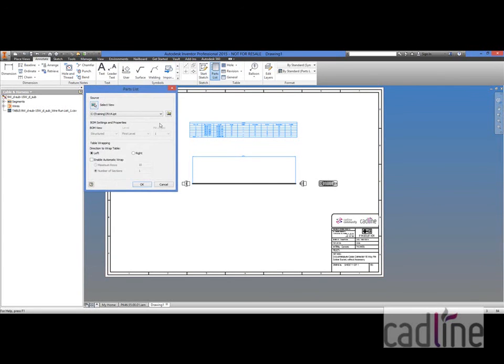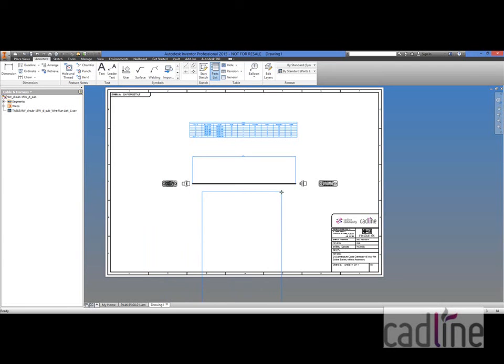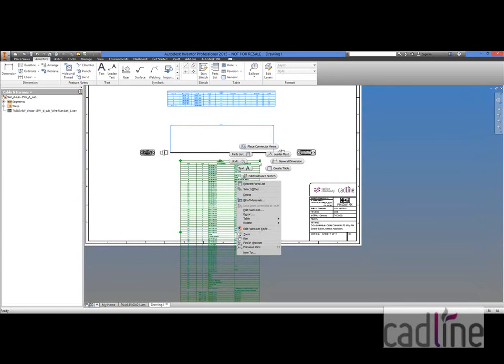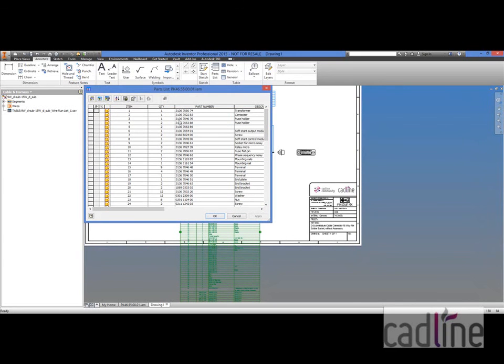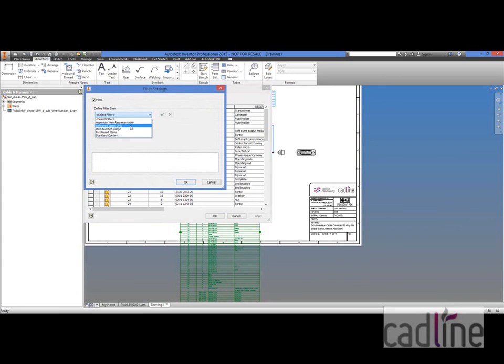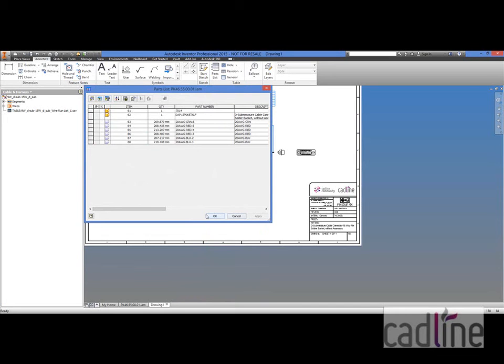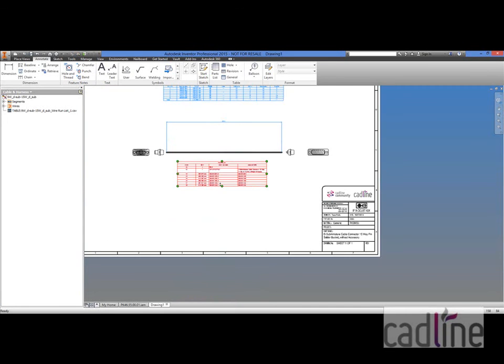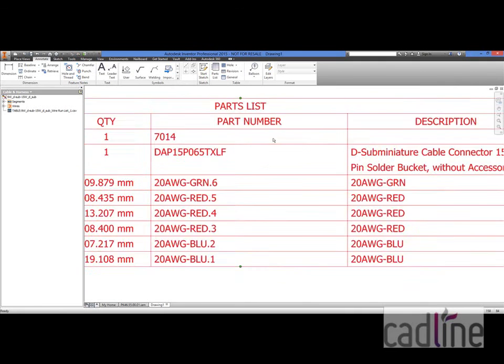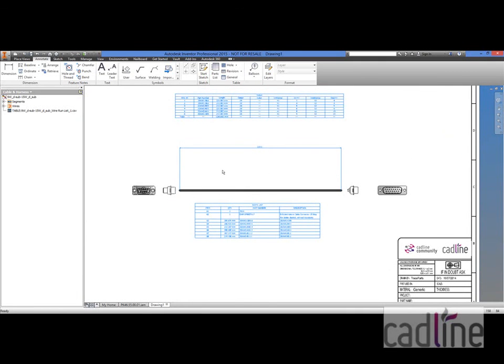So we go to parts list, and we only want parts only. However, we don't want a bill of materials for the entire assembly. So we can view just the components in harness 2. And there we have a bill of materials, a wire run list, connector views, a harness with the true length all produced.